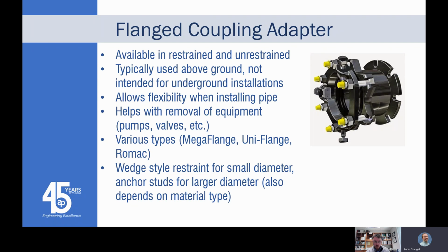Smaller diameter uses the wedge style for restraint that wedge into the pipe. And depending on your pipe material, when you get into the larger sizes, they can use anchor studs where you have to actually drill the pipe, which isn't always ideal. Kind of harder to get them back in place. And just one quick story. I think we're running short on time, but